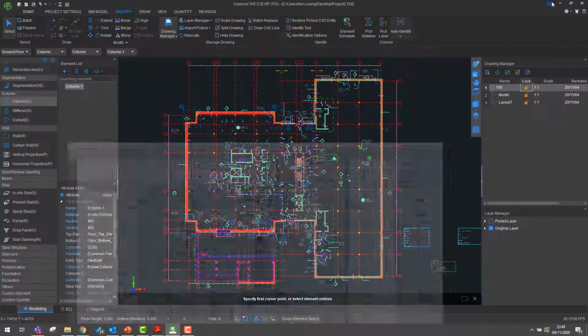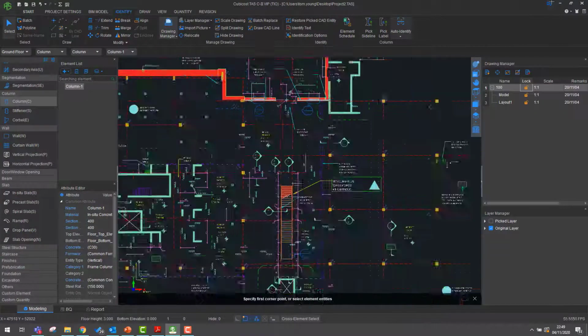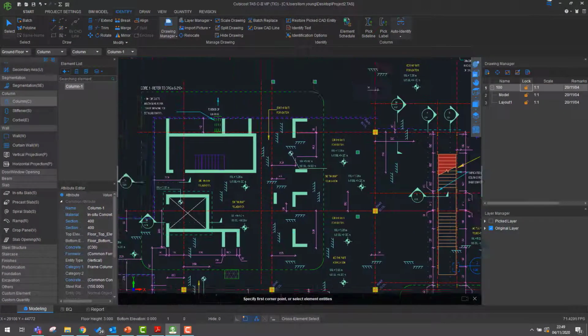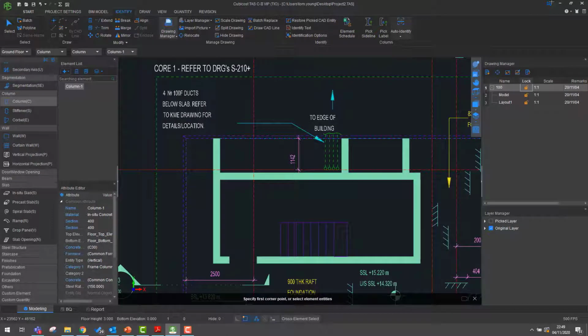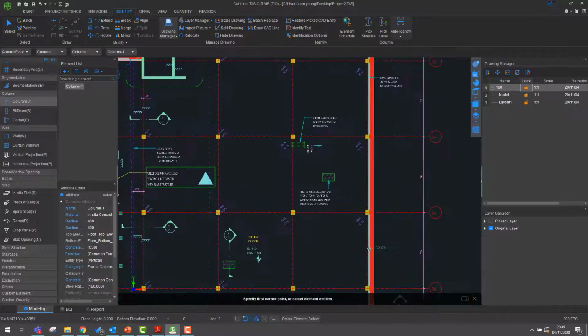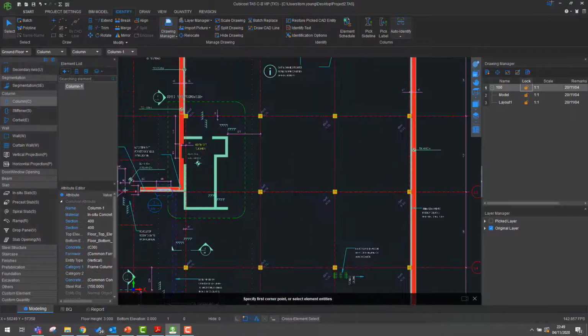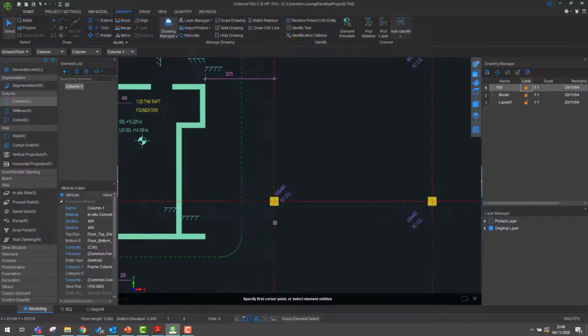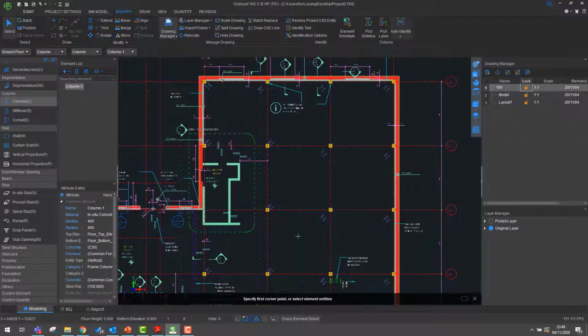So when we bring it through, we digitize it. It takes a few seconds, and we break things down into their various line weights, they're called, and we give them colors based on those line weights so that we can isolate different things. So an example of that is that the walls are green and the columns are yellow. So I have a chance of being able to automatically take them off, which is great.